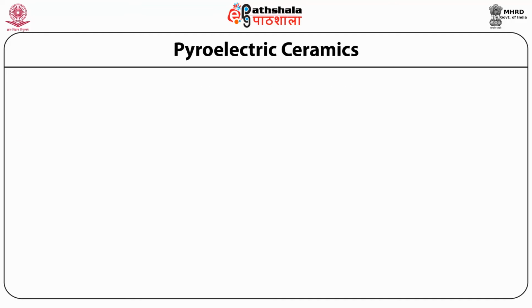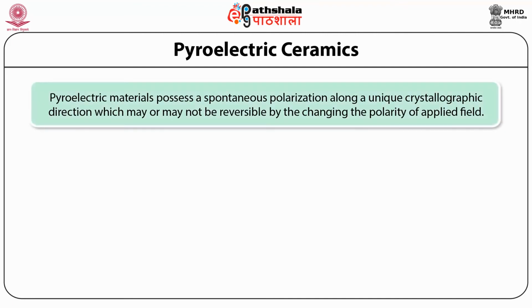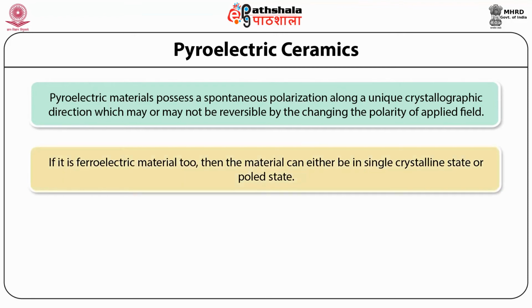So students, now let us discuss what pyroelectrics and pyroelectric ceramics are. Pyroelectric materials possess spontaneous polarization along a unique crystallographic direction, which may or may not be reversible by changing the polarity of the applied field. If the latter is true, then the pyroelectric material is also ferroelectric. If it is a ferroelectric material too, then the material can either be in a single crystalline state or a poled state.